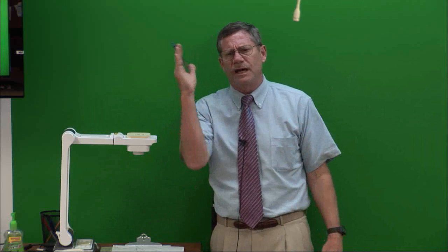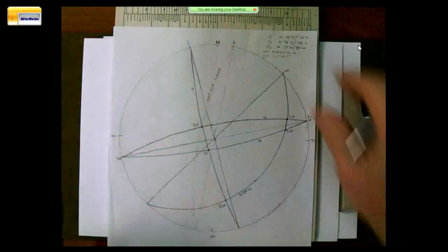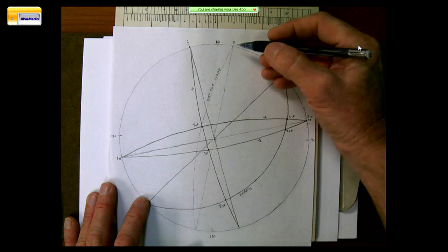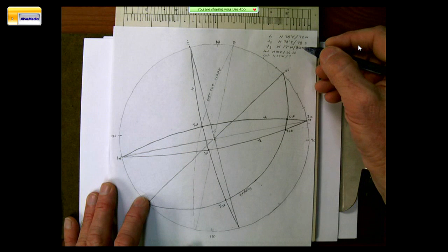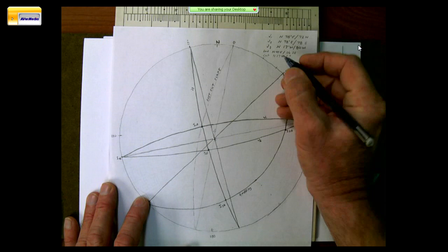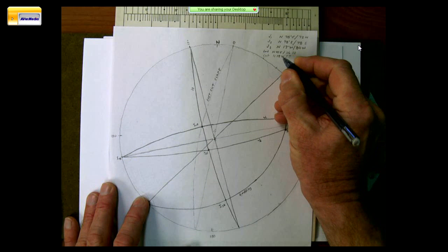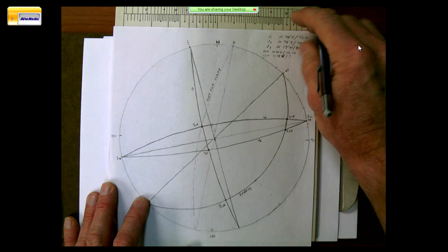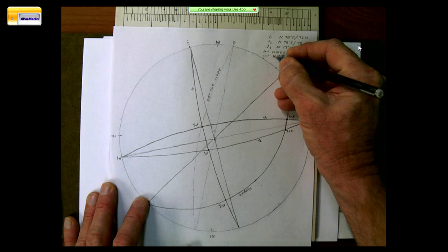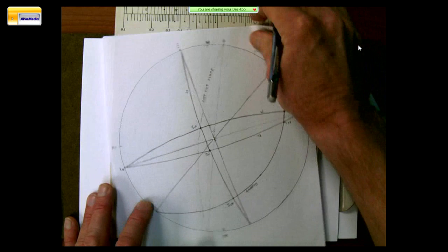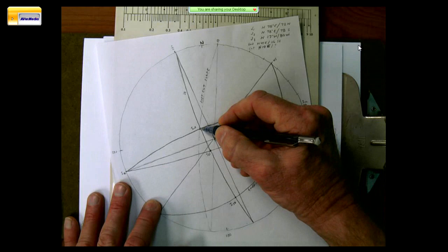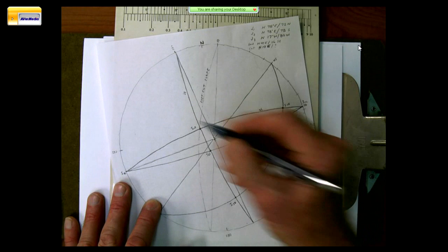How steep can we make this cut slope before we're going to start having some wedge failures? So we count over here, it's north 10 east. The cut is north 10 east. And how steep can it be is the question. So we go, all right, count over 10, rotate just a little bit, get that straight. And now we see there's my first intersection that's going to daylight out of the hill.